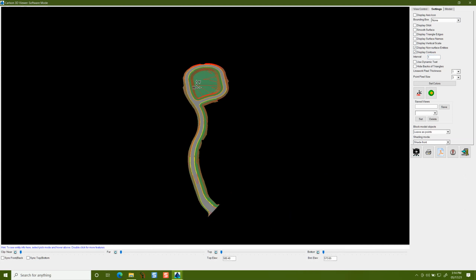If we did do that, if we came in here to change this to make this work, then we have to remember to take this new elevation, calculate 575.78, and use it as the starting elevation of the second one. For right now, maybe we ought to leave it alone. I don't think the town engineer is going to allow a longitudinal road slope less than a half a percent.